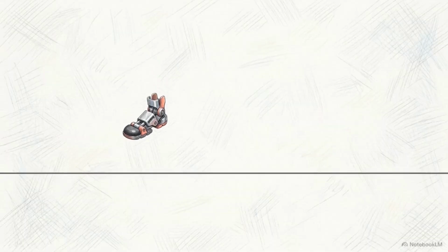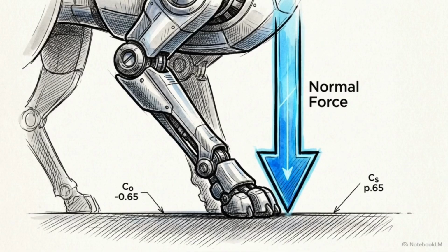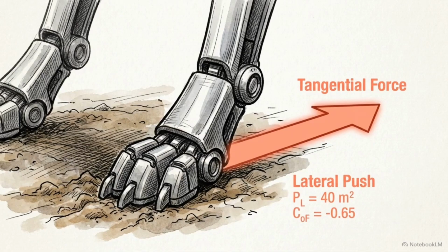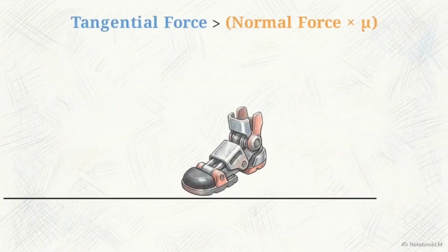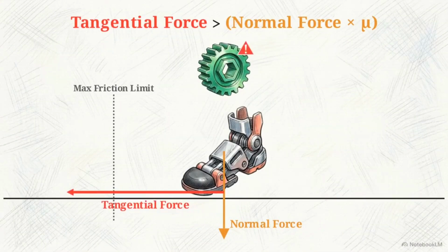This calculation relies on the world plugin providing real-time friction values for the specific ground surface the robot is standing on. Resolving this logic in step 1, before step 2 moves the joints, lets the gait controller instantly adjust the leg's motion to prevent a fall. An external ROS2 controller would only receive the slip data after the robot's balance had already been fatally compromised.